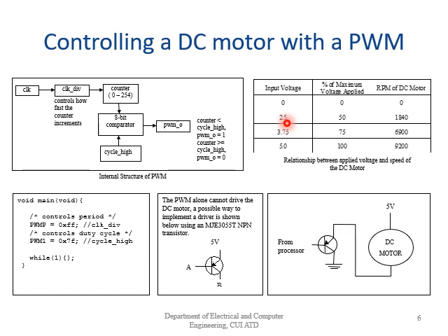So now you can see here that PWM alone cannot drive the DC motor. So here we have a MOSFET, and this MOSFET is going to drive the DC motor. The signal will come from the processor and will be applied at the gate of the MOSFET, and what we are going to apply at the gate will be the pulses of the pulse width modulator, and then the DC motor will be driven.